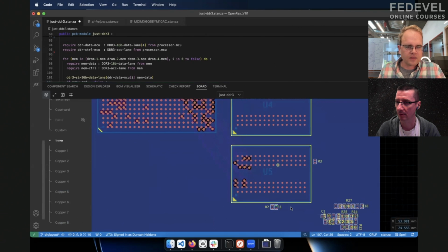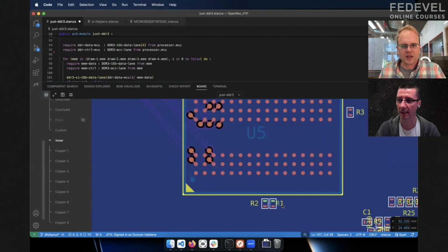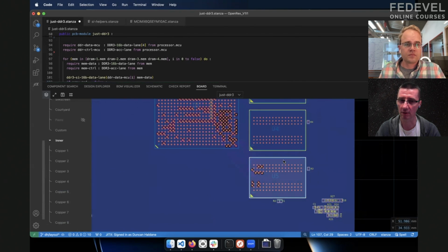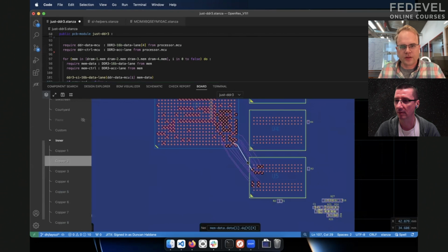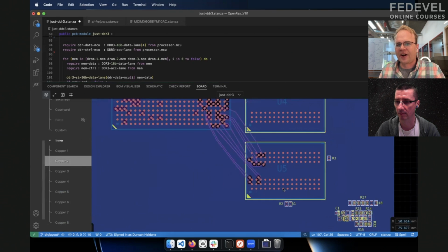All right, well, let's try. They need to be length matched to the DQS, the differential pair. Clock just needs to be longer. So there's a constraint on DQS within the byte lane, and then there are also constraints on the clock. Right now it's not routed, so I don't know how to length match this. Oh, actually, I think a team member created this design.